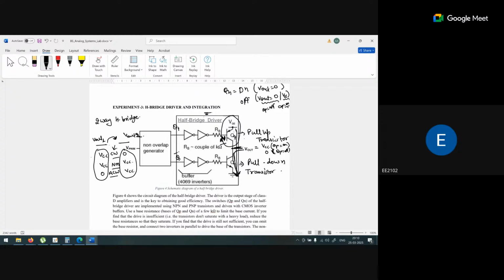That particular single circuit is called a single H bridge. In the L293D, if you are aware of this IC L293D, we are having 4 H bridges. 2 H bridges will be used for one motor, and 2 H bridges will be used for the other. So we can connect 2 motors at a time with the L293D.